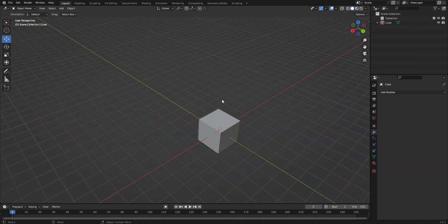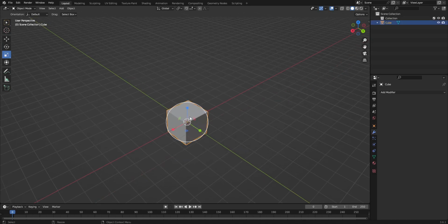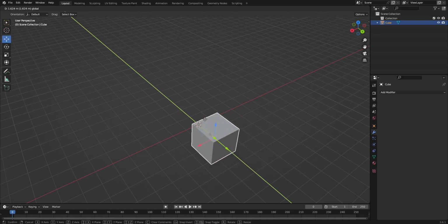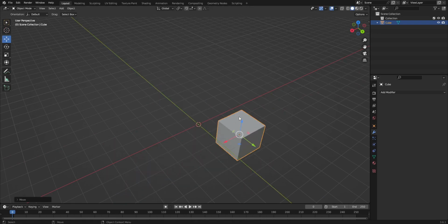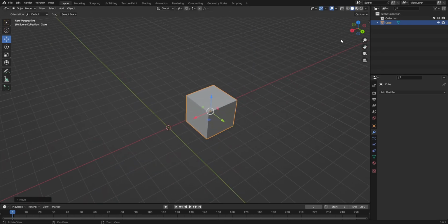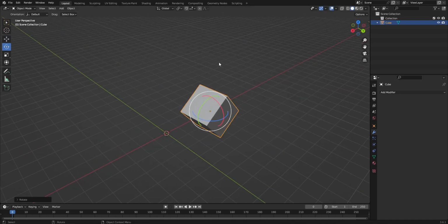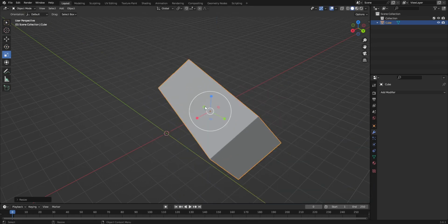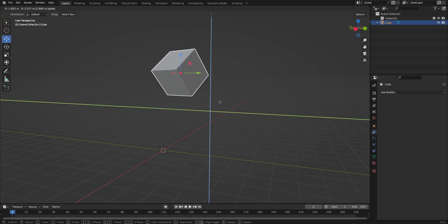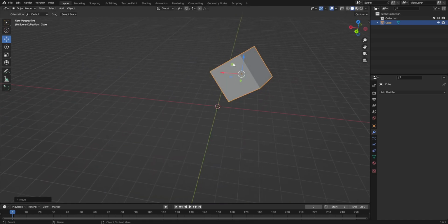We can control our 3D board and objects by using gizmos, which are located on the left side. It is enough to select an object and the related gizmo will appear. We can move it in different axes, which are X in red, Y in green, and Z in blue. However, I cannot see the Z axis in my scene. I can rotate, I can scale it up and down, and move between 2 axes simultaneously, such as Z and Y.